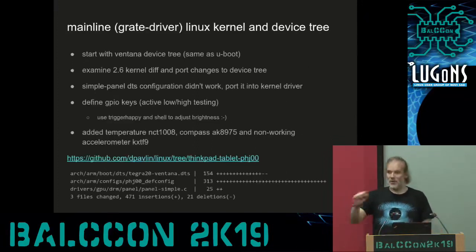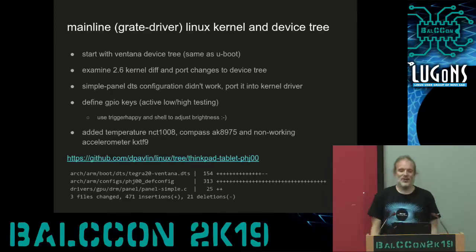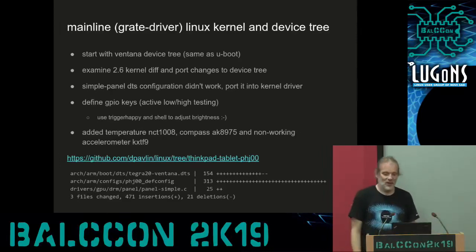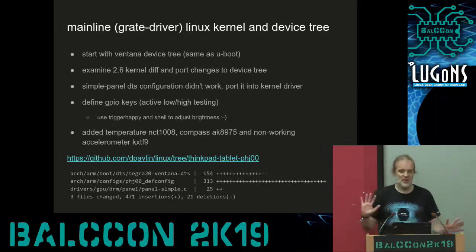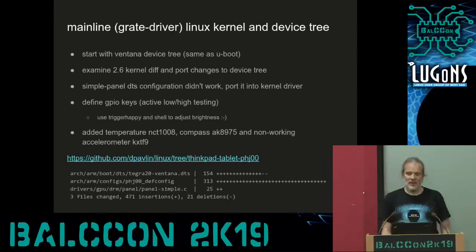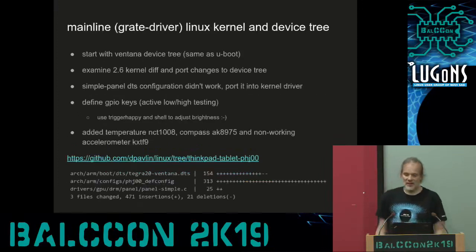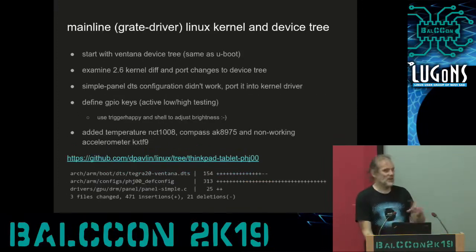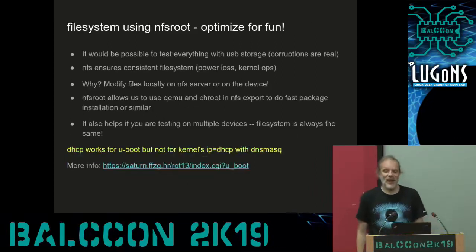Then I said, oh, this is very good. I have U-boot, now the kernel. So I got to the GitHub, compiled the kernel, again, did some minor changes like defining sensors, GPIO keys, and stuff like that. And in less than 400 lines, I actually had a booting system. I thought that the next slide, this is the picture of the booting system, but it will come later.